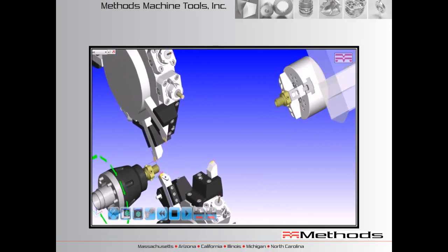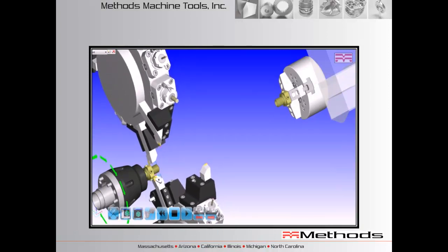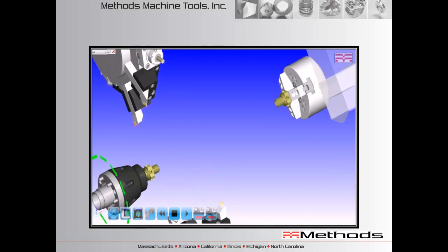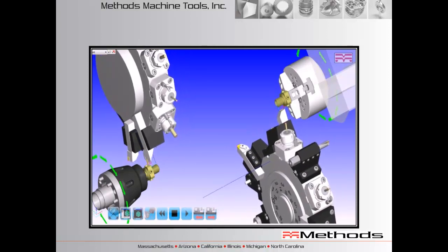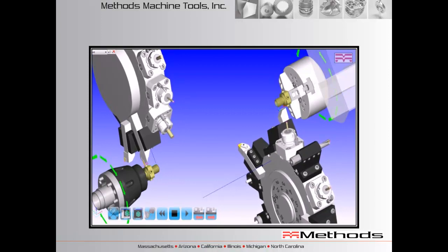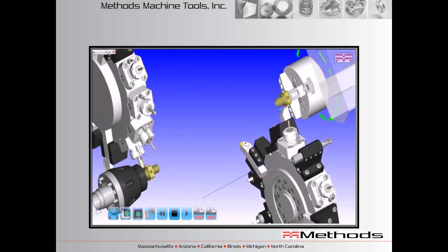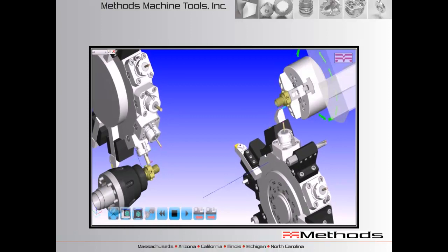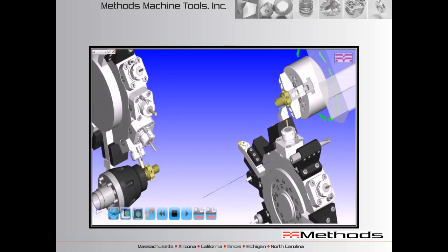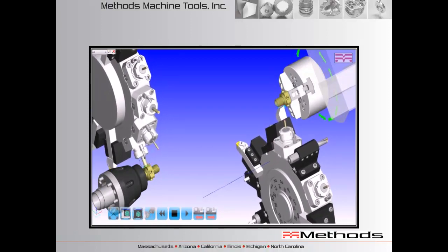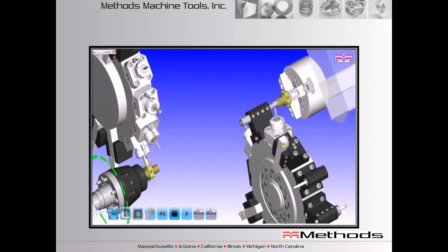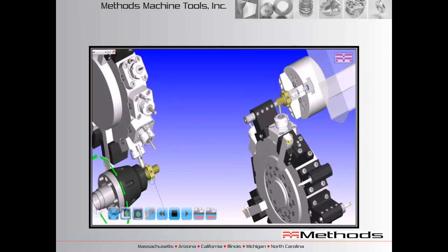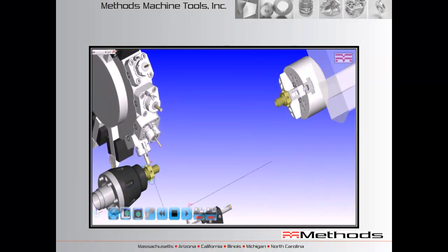This is just a sample of a number of tool paths put together. Here I'm pinch turning an OD, and then I'm facing and finishing and rough turning the other side. Each one of these tool paths was generated independently, and then I went ahead and put them in. I'm milling the lobes on the left while I'm finishing up turning on the right. I have the ability to take all these tool paths, move them and reorder them to balance my cutting on the left and the right.